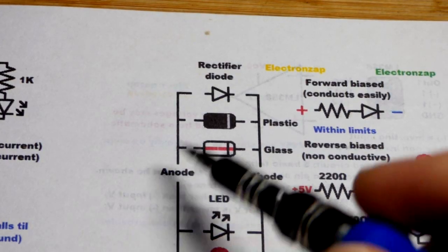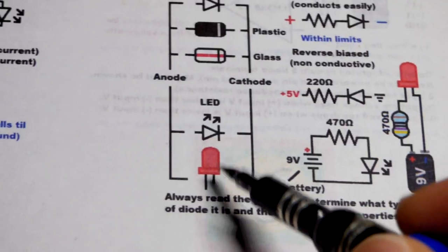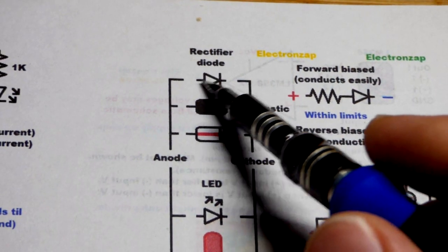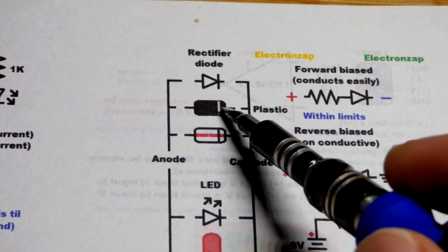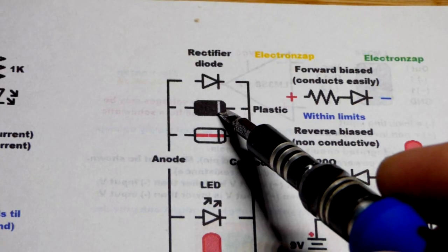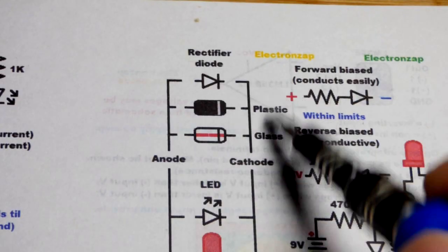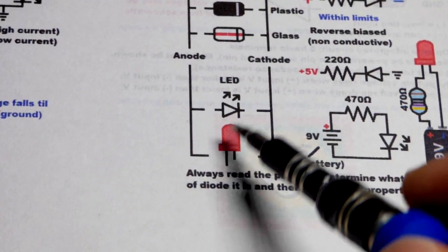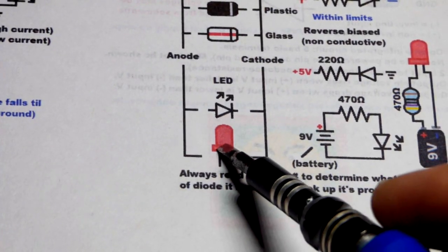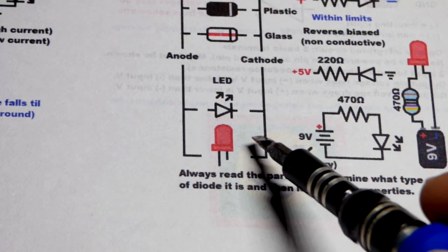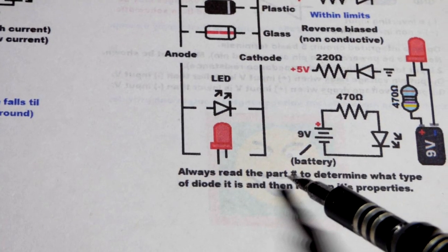So now, diodes are common components in electronics, mostly the LEDs these days though, but also there's a lot of important diodes. So rectifier diodes, this is the basic symbol right there. It may come in the plastic package. Cathode is where the band is, or the glass package right there. Anode over here, that's how you indicate those. When it comes to the LED, the anode usually has a longer lead, cathode shorter lead, and often a little shaved edge right there. Again, the symbol.